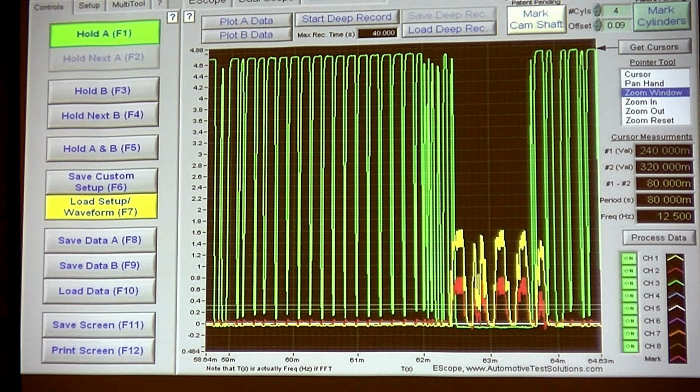What do you think? Do you think that the red and yellow look like a good CAN-C signal? We don't know very much, but I know that that's not going to work, right? So basically, the reason that I had codes from the low-speed system is because it's a different system, isn't it? That's GM LAN, which is CAN, right? Single wire application, J2719. So basically, this is just a different thing, right? That's all it is. But I can talk on that bus. I can't talk on the high-speed bus.